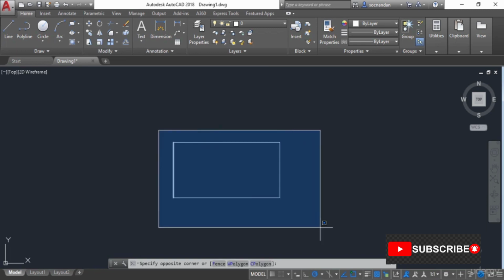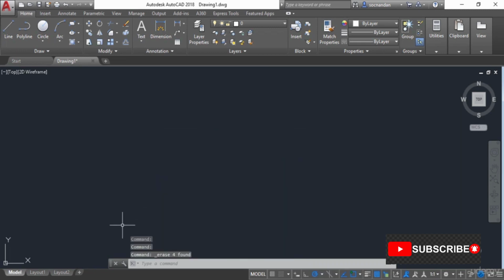So let's now erase this complete rectangle, and now we'll bring this UCS into the drawing area. In order to bring it directly, you can click on this zoom extents option, and now you can bring it here. Now we will again make the same rectangle of length 10 units and width 5 units, but this time instead of using direct distances, we will use coordinates. So let's go to the line command, and let's start the rectangle from the origin.